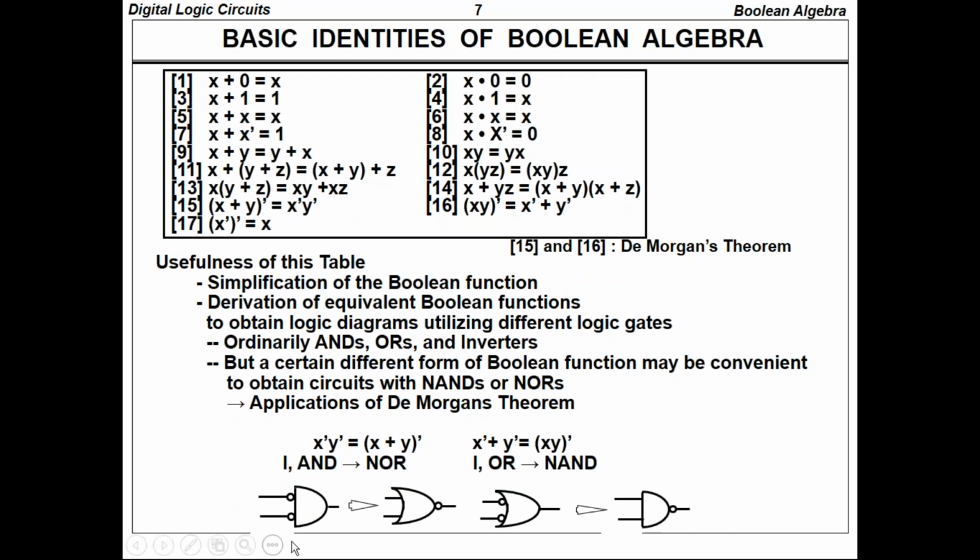Yes. So you are having two expressions x and y, and the Boolean algebra states that x bar plus y bar is equal to x into y the whole bar, and x bar into y bar is equal to x plus y the whole bar. So these are the actual two expressions. By that we are able to generate our universal gates from the expressions. So that's why we are using De Morgan's law for changing our gates into any form, that means either into pure NAND or pure NOR implementation.